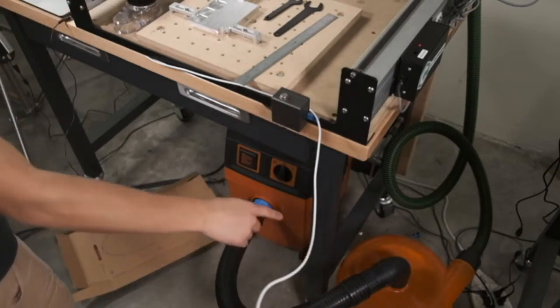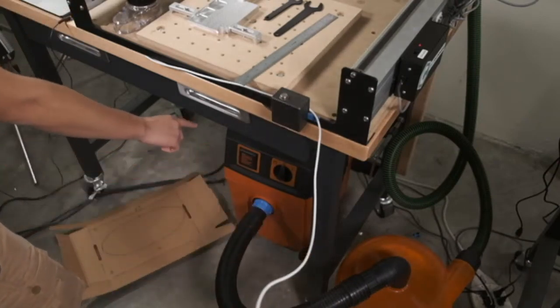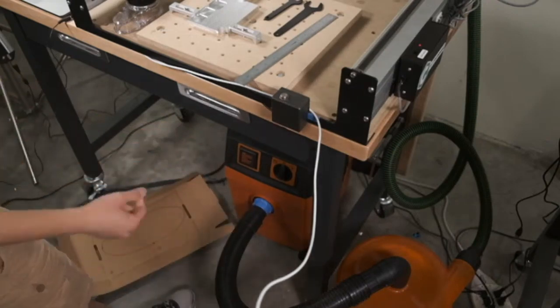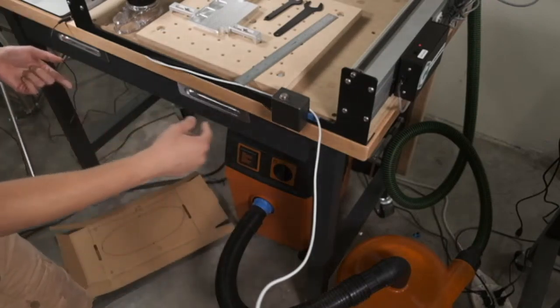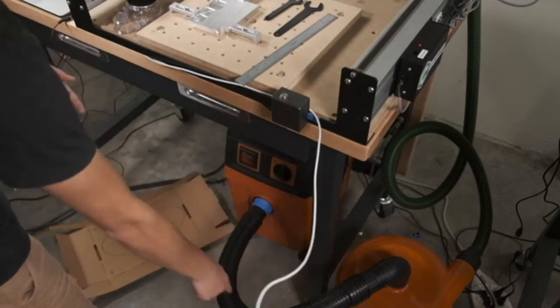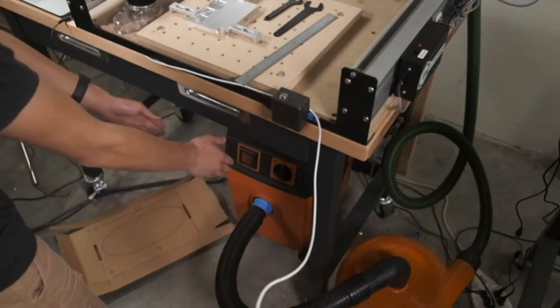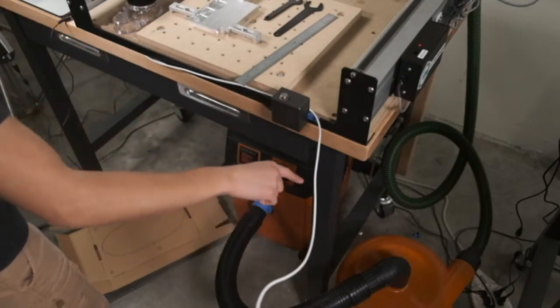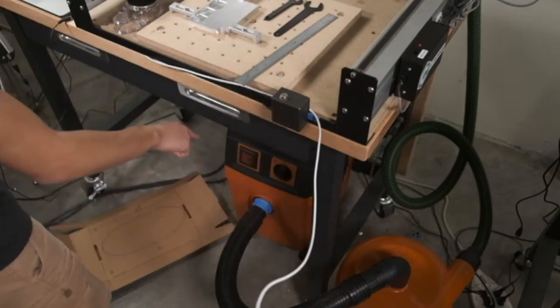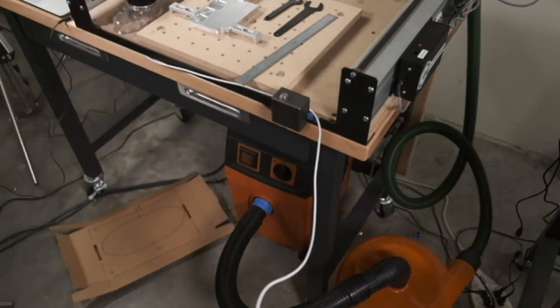Dust separators will really save your vacuum, because it has a limited capacity and the fine dust will clog it. Dust will fall out here. It doesn't clog the tubing. It doesn't clog a filter. So this saves this. I highly recommend having something in series before your vacuum coming off your CNC.